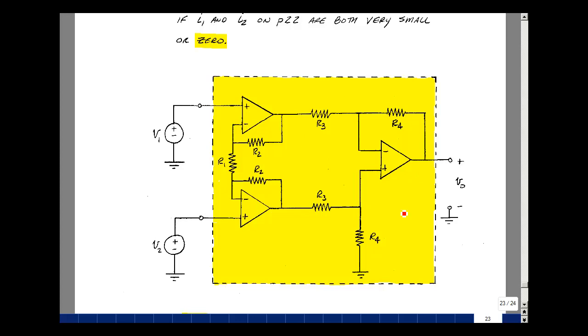Now, differential amplifiers are often used to measure voltage across a floating load. In other words, things that are not grounded at either terminal. This is particularly true when trying to measure something like an EKG. I'm taking a difference of two voltages with sensors across someone's chest to pick up a heartbeat.